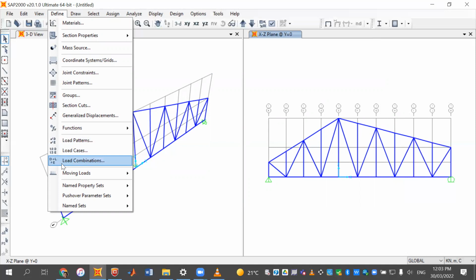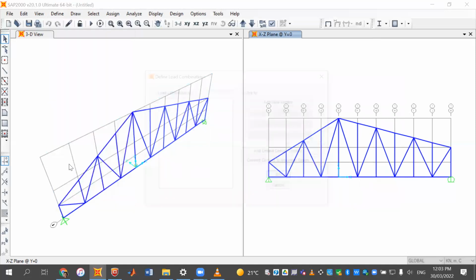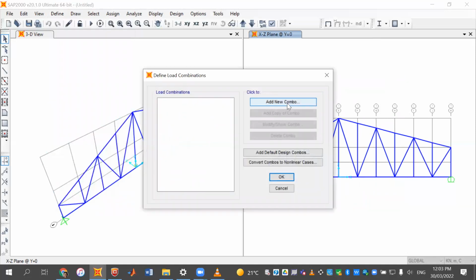So next, we are going to define the load combination. Here we define our load combinations, or combinations of actions, based on a standard. So what you need to do is to open this standard 1170.0, which is the general part.